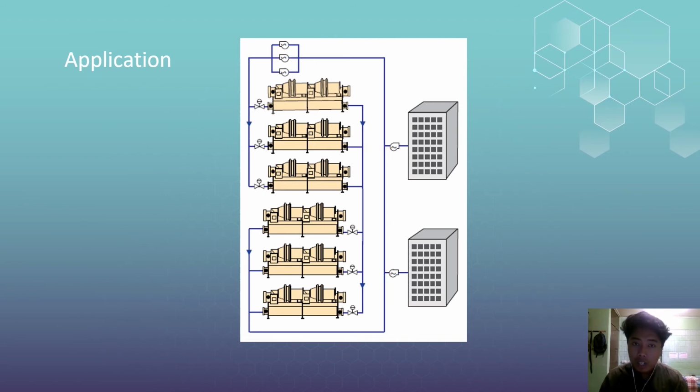Another type of large chilled water system could actually start out as more than one chilled water system. An existing set of buildings can be gradually added to the central system, or two geographically distant chilled water systems can be connected. As system load drops, chillers are turned off.